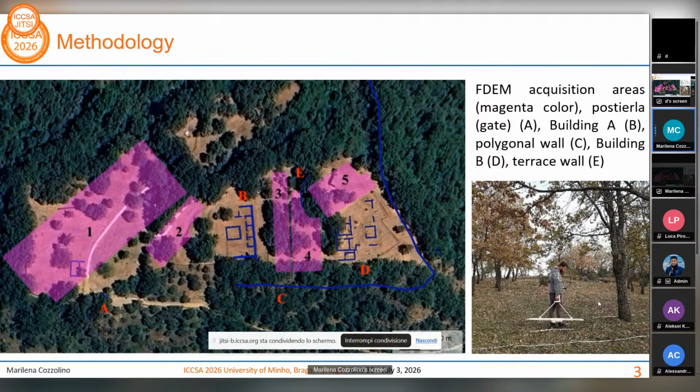As regards the geophysical prospection, data acquisition was carried out using a GSSI profiler. In order to maximize sensitivity to fluctuation and shallow conductivity, measurements were taken in continuous mode with vertically aligned dipoles. We used frequencies between 2 and 15 kilohertz.